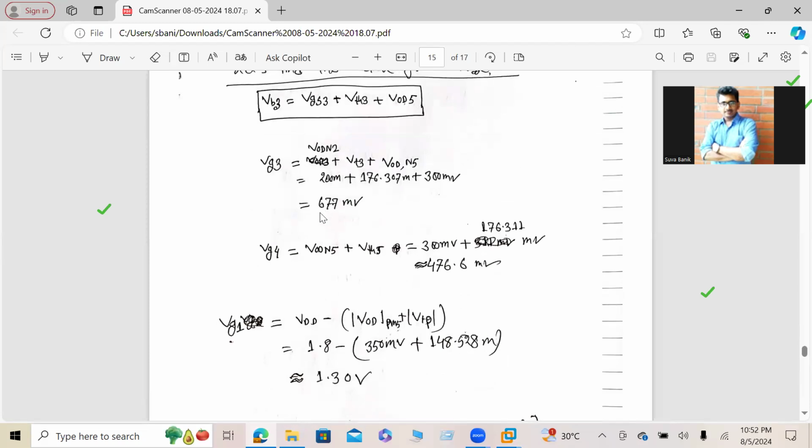So I just tweak the circuit. How do I tweak? I just take the help of IV curves. I explained how we can play with the circuit in my lecture number 4, especially when I designed the Cascode OPAMP. In this video, you saw that we can take help of the IV curve, and this curve will tell us what my gate voltage should be to keep both transistors in saturation. So we don't need to worry about that. This curve will tell us when this transistor goes in saturation.